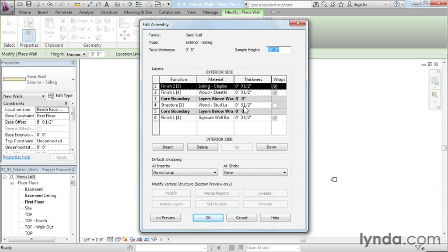In this case, I was saying that this is a 2x4 wall, and this says this is 3.5 inches thick. And that is true because your typical 2x4, once it goes through the milling process, ends up getting down to about 3.5 inches by 1.5 inches in size. So it's not actually 2x4, it's something just a little bit smaller. And you can see here, whether it's the siding or the sheathing or whatever the case may be, each material inside of this wall has its own real-life thickness associated with it. In reality, this wall is a total of 5 inches thick, but we're still going to call it, or at least I'll probably still call it, a 2x4 wall because that's really the terminology for it.